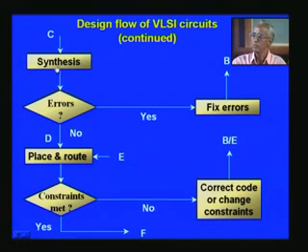And if you encounter errors here also, the type of errors that may come in is that you might have given a frequency of operation that is a very high value, and what could be achieved on a particular target FPGA is not able to match the speed you have specified. So it may also give a compiler error and setup and hold time violation.